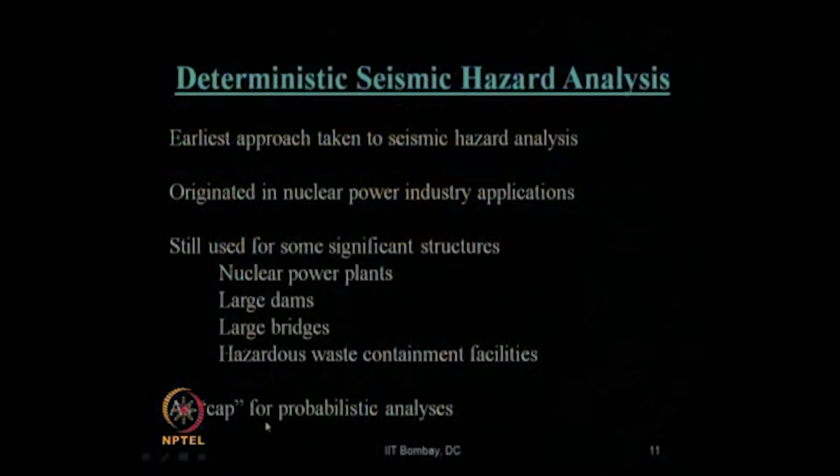That is the reason why deterministic seismic hazard analysis values are called the cap, or maximum, of the probabilistic seismic hazard value. That is why you can see over here it is mentioned in this slide as a cap for probabilistic analysis. Suppose after doing the analysis, your probabilistic seismic hazard value is higher than the deterministic seismic hazard analysis; that shows you have made a mistake in your calculation. That is the only conclusion one can draw from the results.